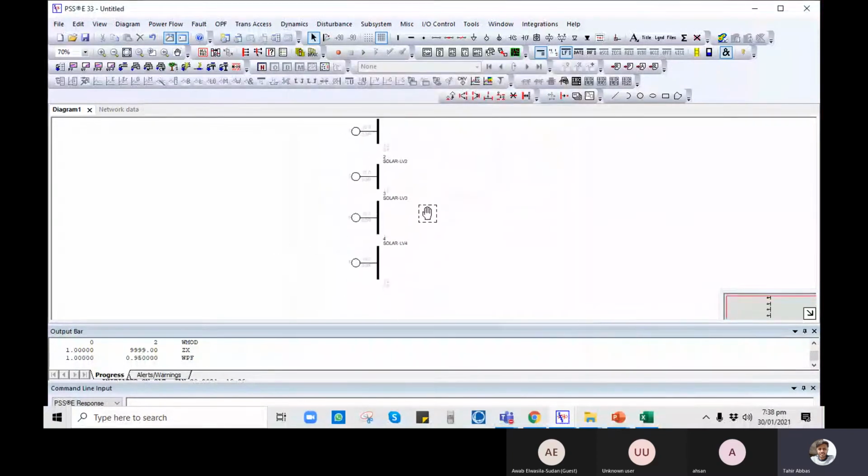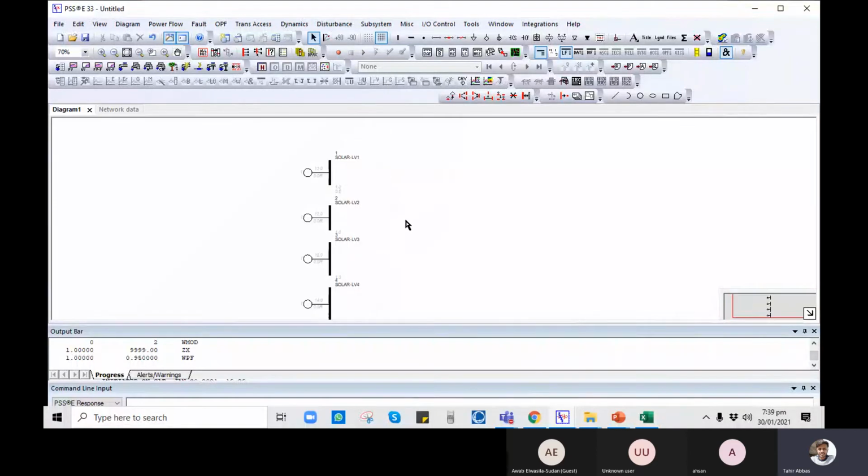Now in this way you have basically covered the generator modeling only up to the generator point, because there is a whole substation for the solar farm. Inside the layout we have modeled 4 collector groups, basically 4 inverters in PSSE: the first for 12 megawatt, the next 12 megawatt, 12, and then 14 megawatt. So the next thing is the LV.